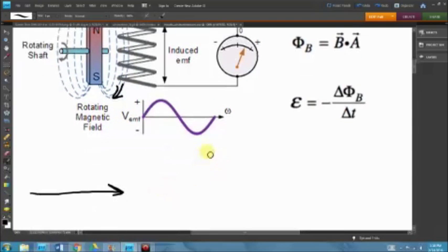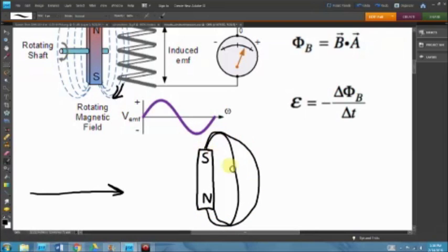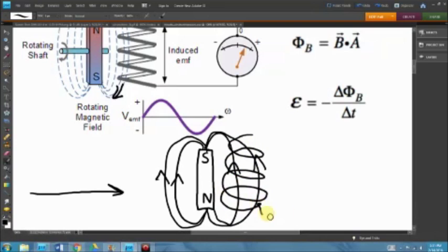But if we do move it, let's say wind pushes the fans and turns it like this. Now we got field lines going in the opposite direction. Of course, there's field lines over here too, but they don't really matter that much. So, you got your coil of wire. Well, why does this create a voltage? It's just another magnetic field line. Well, yes and no. It's different because you've had a change in flux over time.